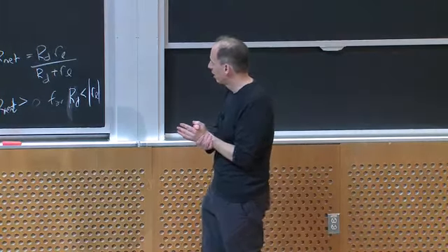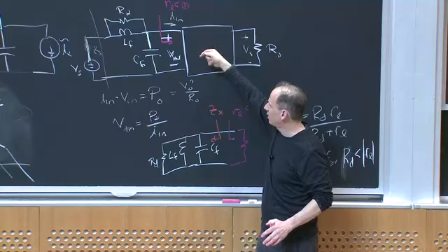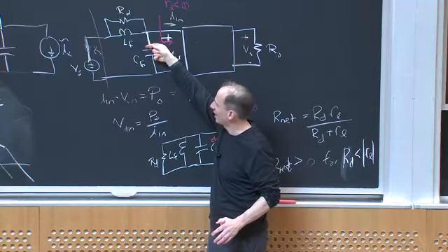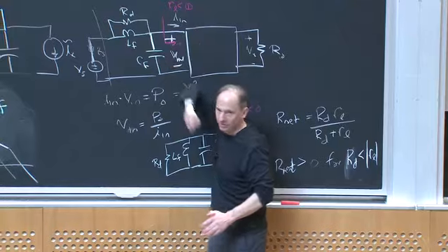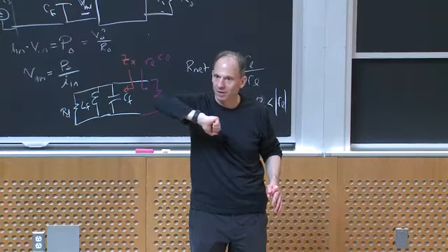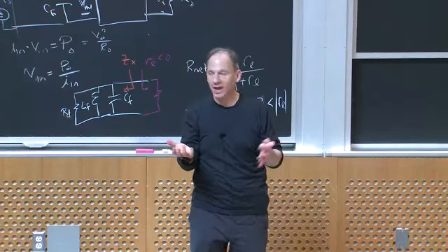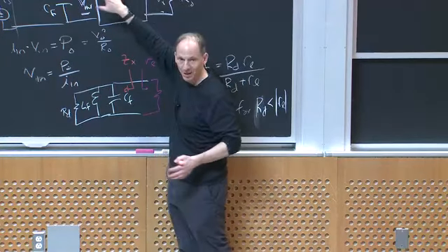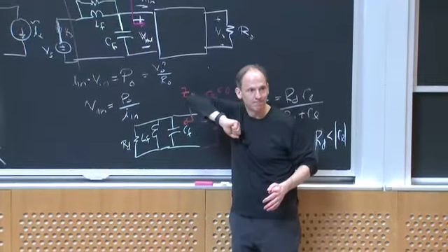First, if I assume my converter operates perfectly, we would like the maximum value of the output impedance of my filter, Zx, to be much less than the magnitude of the negative input resistance if I have perfect control. And that would be the case if I had a perfect converter with infinite bandwidth in controlling the output anyway. So I need to meet that requirement.